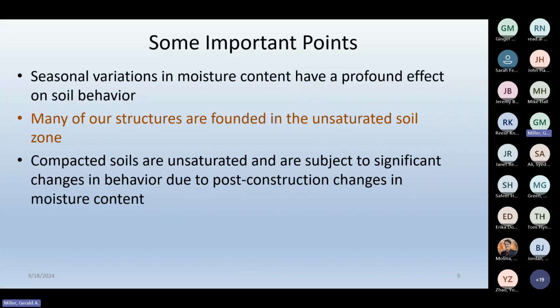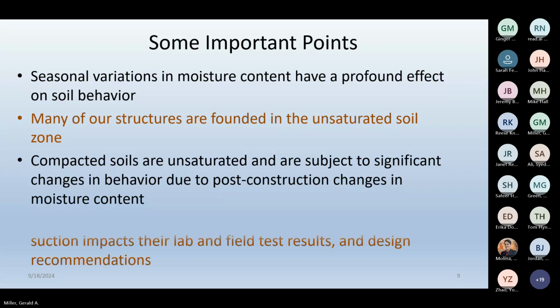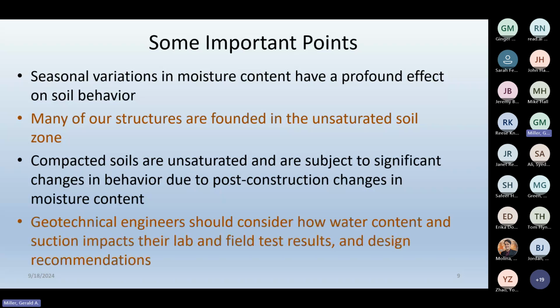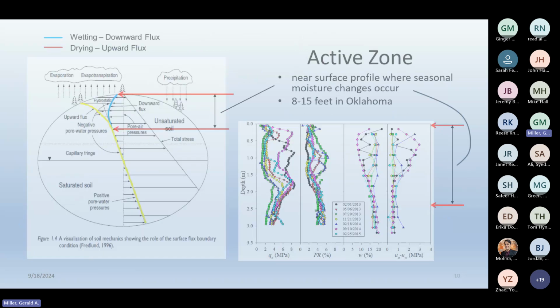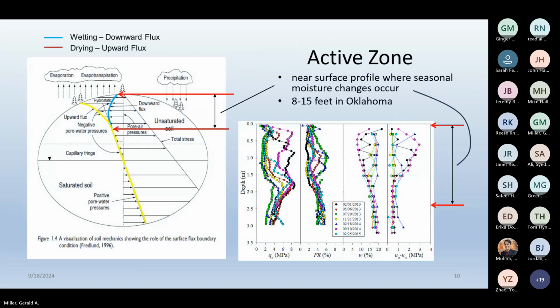So it's real important to think of compacted soils as unsaturated soils subject to changing behavior due to changes in moisture content. And then this is sort of the big takeaway. Geotechnical engineers should consider how water content and suction impacts their lab and field tests and their design recommendations. Okay, so now some basic concepts to go along with this.